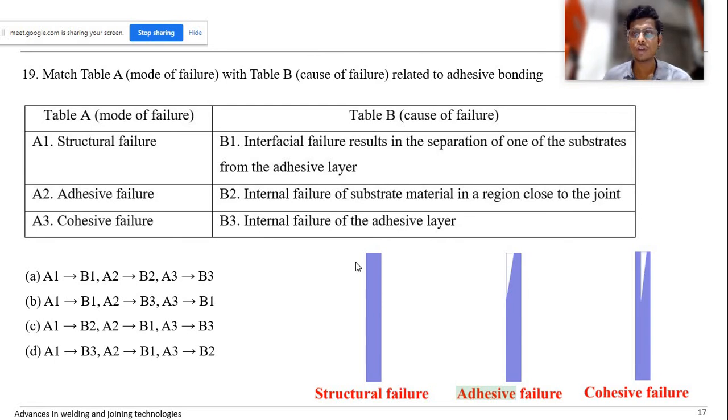With respect to casting, in that sand will be there, sand with the mold. If it is joining, then it is called the adhesive property of the molding sand. But in the molding sand itself, there will be a joint because of the clay and all. That is called the cohesive property of the molding sand. Similarly, cohesive means within the material, adhesive is between 2 different materials.